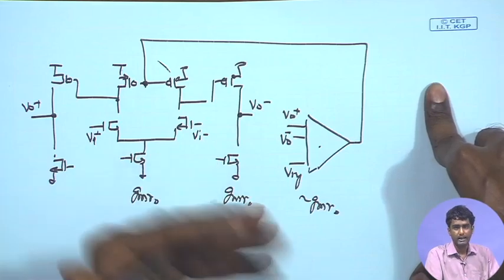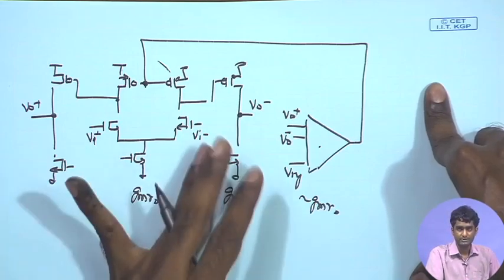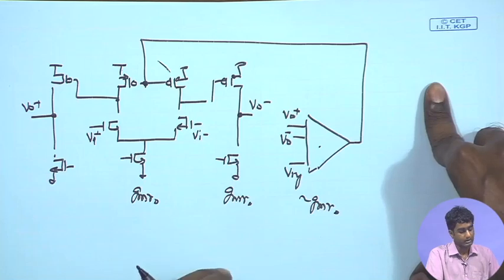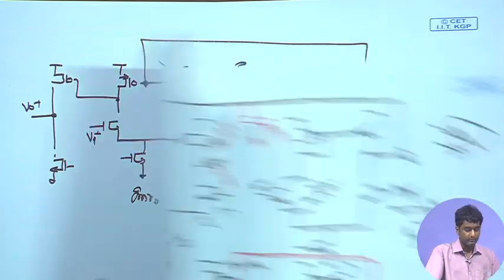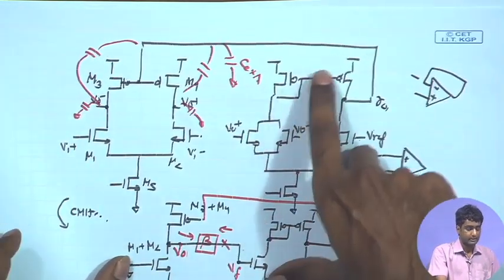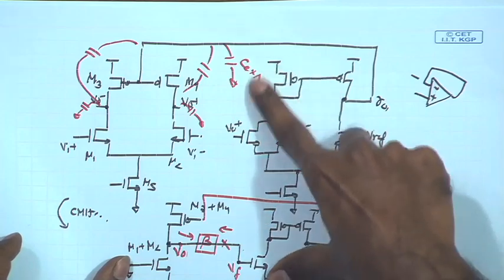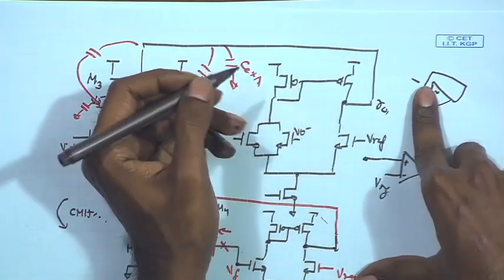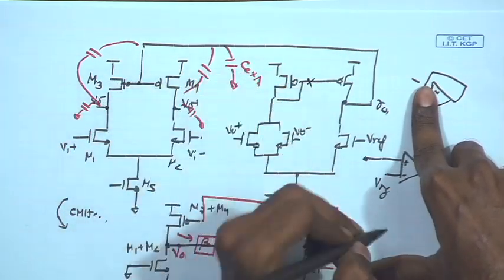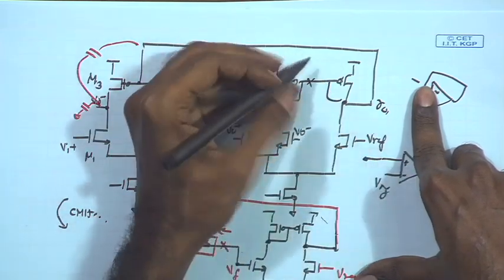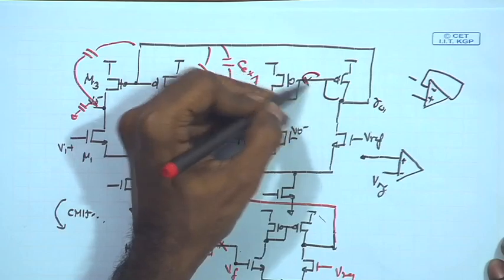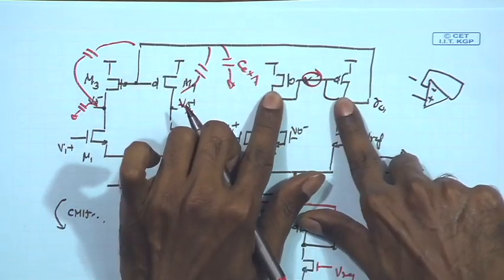Whenever you have larger gain in the loop, it can make the system a lot more unstable. So, in that case, if we want to be safer, we can get rid of this current mirror load and rather use a diode connected load. Basically, we can reduce the load of our error amplifier, eliminate this interconnection, and just go for diode connected load on both sides.